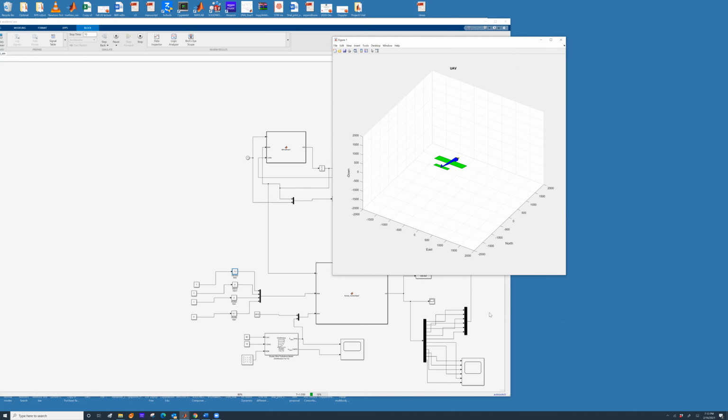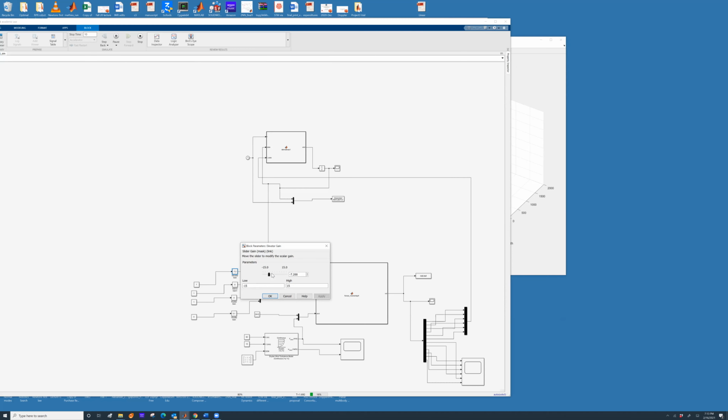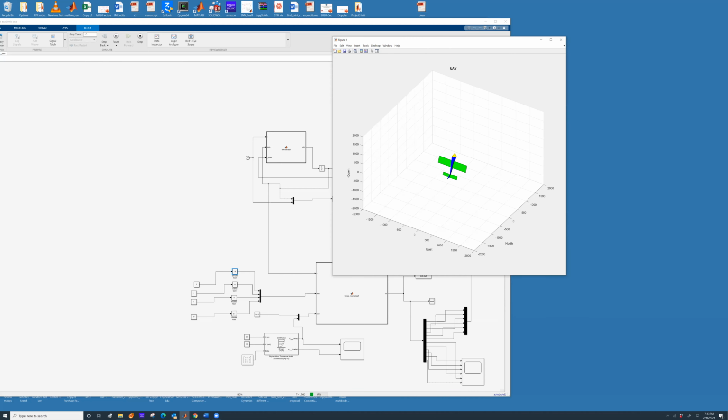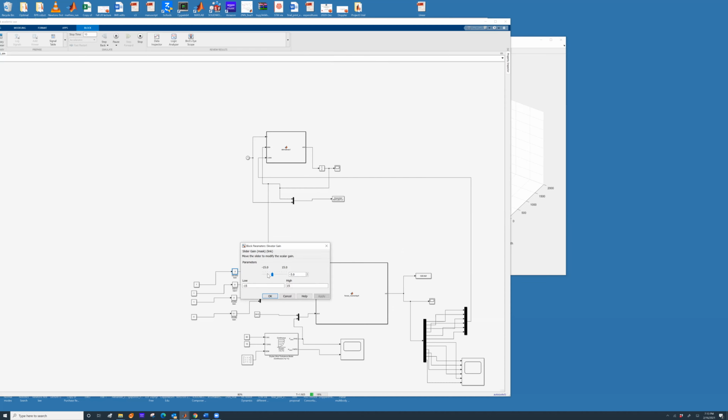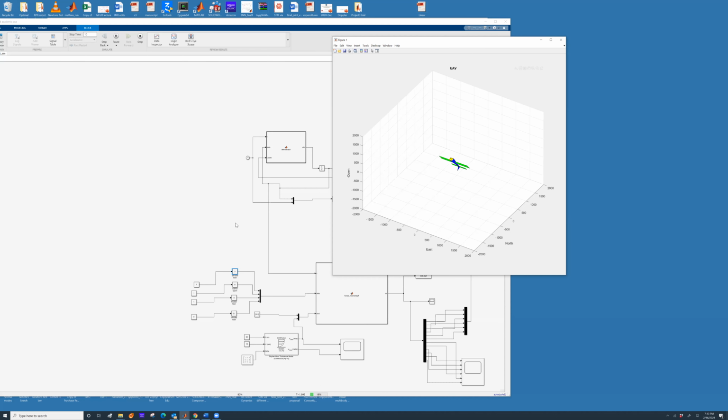Okay, I'm going to stop here, but I'm going to ask if there are any questions. Now the aircraft is climbing, and I want it to stop. If I want the aircraft to stop climbing, I would change the values of the elevator gain, and you will notice, oh, this is too little, and the aircraft will actually go back to its own.